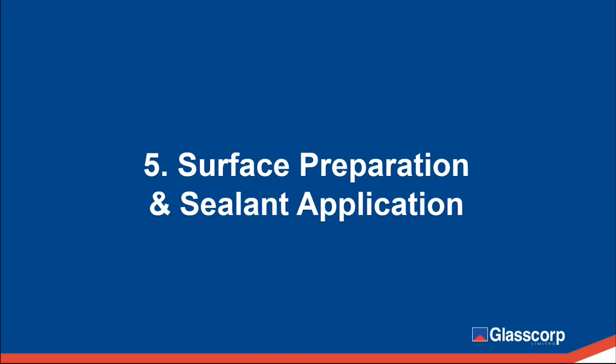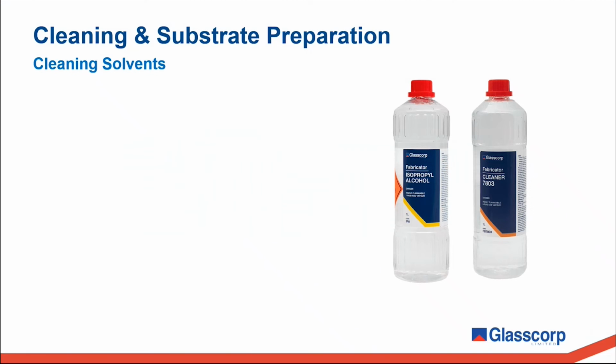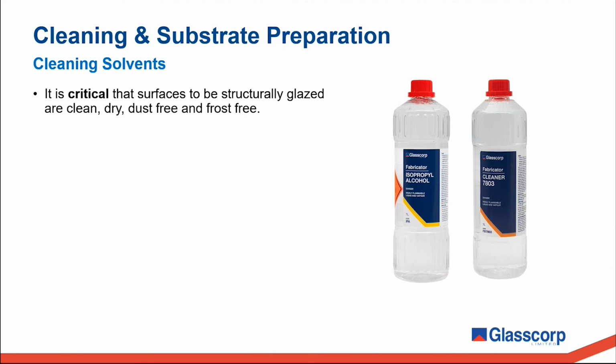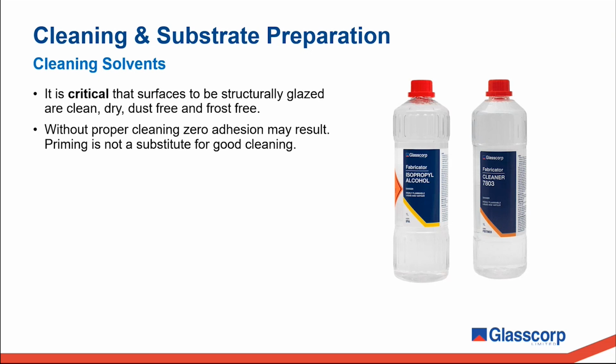In this final section, I'll cover important points relating to correct surface preparation and sealant application. Correct substrate cleaning is important for standard sealant applications. In structural glazing applications, it's critical. The most common cause for adhesion failure is poor preparation and cleaning. Priming is not a replacement for good cleaning.